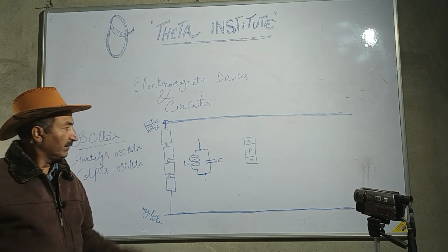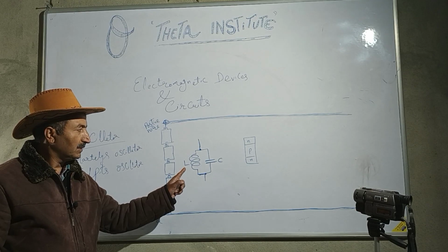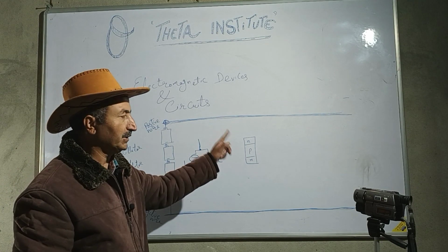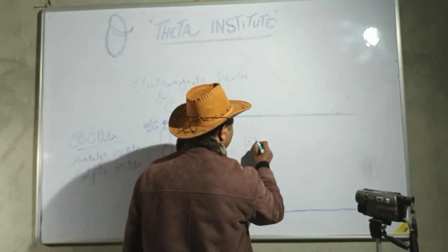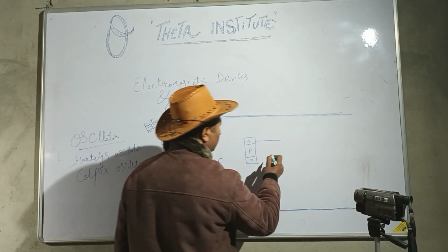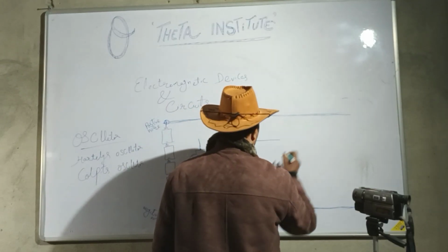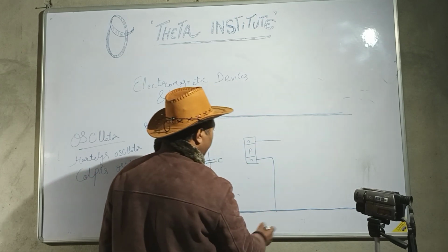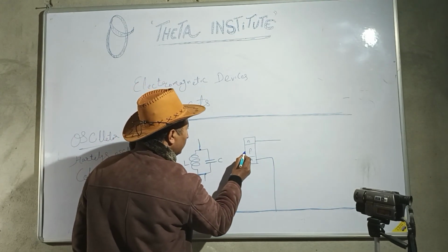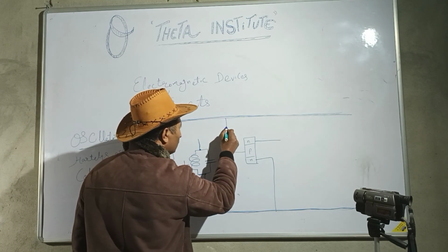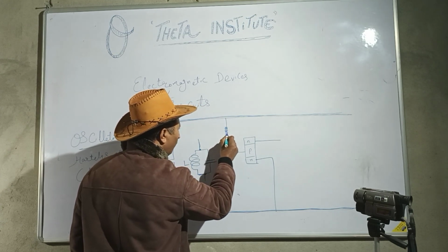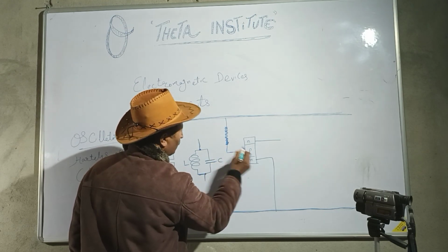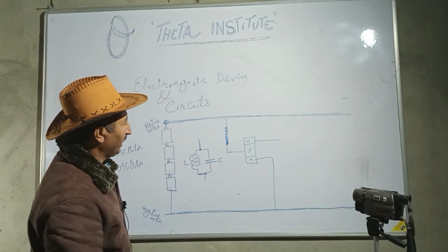Now make these oscillations be amplified by this transistor. It needs that this be given directly to negative, and this be given to positive but through a high resistance, so that only a small voltage will flow to P, to the base.